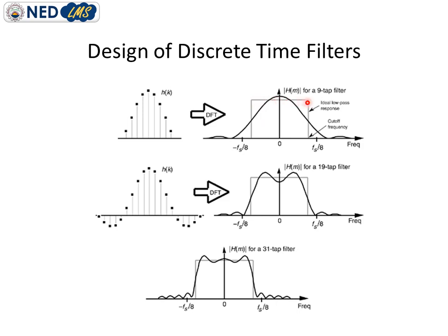But as I am not utilizing all the filter coefficients to design the filter, I am getting this response which is close to the low pass filter but not the ideal or perfect one. From this you can see that the frequencies that should be attenuated are not fully attenuated, and the frequencies that should pass are also attenuated, which is not acceptable in the ideal response of a low pass filter.